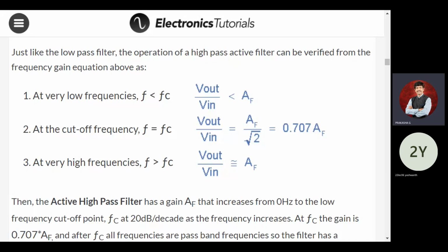Don't get confused with R1 there also, R1 at the bottom also. The inverting terminal is connected with R1 and RF. The non-inverting terminal is connected with the two resistors and two capacitors, represented by C2 and C3. In the low pass filter, we use R1, R2, C1, C2. But here we use R2, R3.